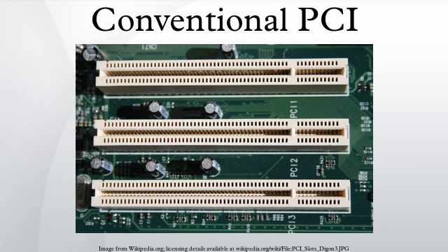Mini PCI. Mini PCI was added to PCI version 2.2 for use in laptops. It uses a 32-bit, 33 MHz bus with powered connections and support for bus mastering and DMA. The standard size for mini PCI cards is approximately a quarter of their full-sized counterparts. As there is no access to the card from outside the case, unlike desktop PCI cards with brackets carrying connectors, there are limitations on the functions they may perform.